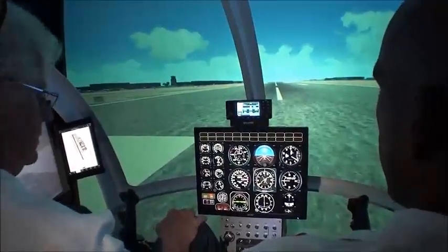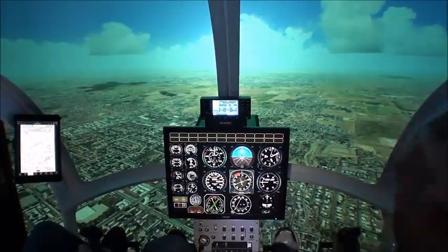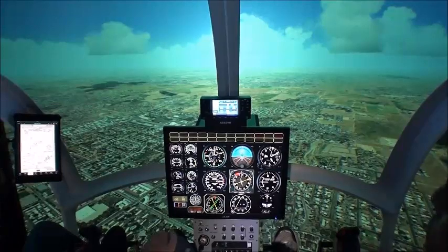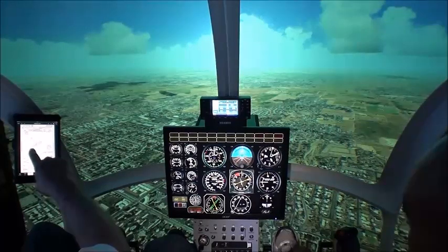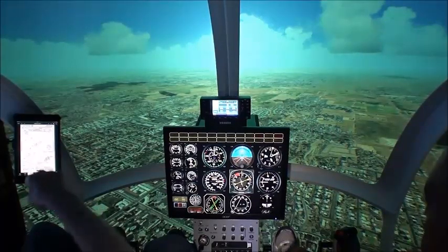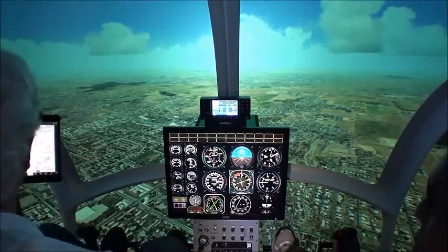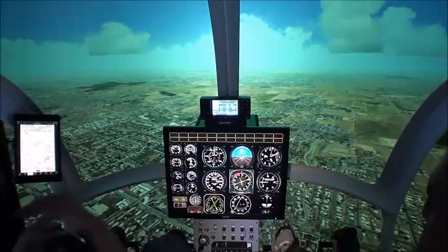All right, so the only thing, okay, camera on. Okay, we're going to fly the NDB approach at Chandler, Arizona, and it's 050 outbound to do a procedure turn, go back in at 230. Oh, it's 050 inbound, so it's 230 outbound.